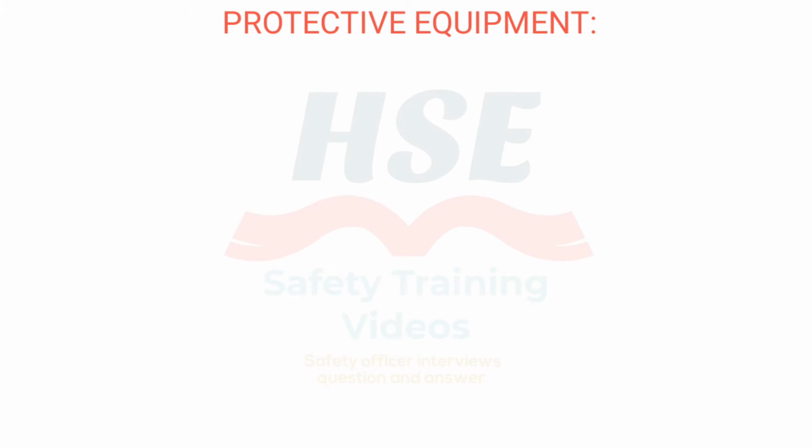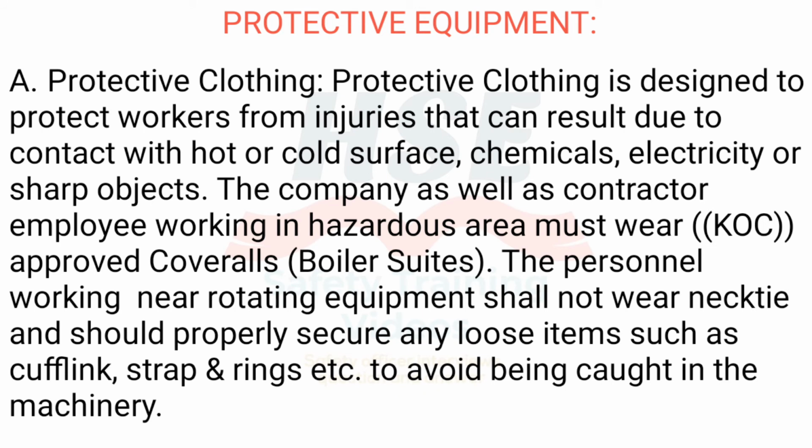4.2 Protective equipment. A. Protective clothing. Protective clothing is designed to protect workers from injuries that can result due to contact with hot or cold surface, chemicals, electricity or sharp objects. The company as well as contractor employee working in hazardous area must wear KOC approved coveralls, boiler suits. The personnel working near rotating equipment shall not wear necktie and should properly secure any loose items such as cufflink, strap and rings etc. to avoid being caught in the machinery.